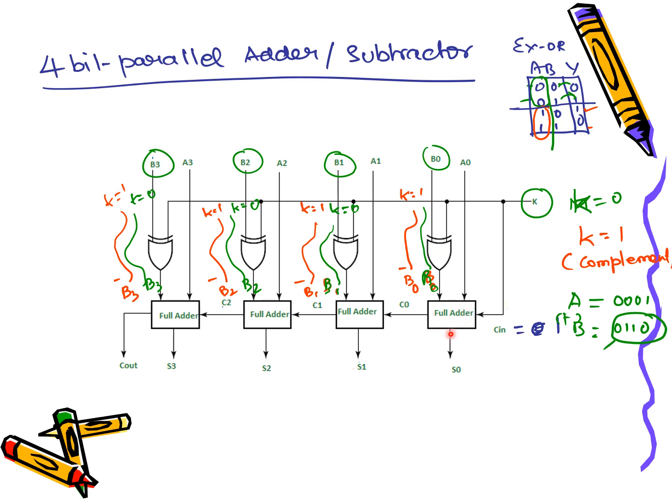So one full adder has at least 3 different gates, each of which will take its own time, say suppose 30 nanoseconds. Now imagine how many stages of additions you will have, and for that many times it has to wait to propagate and produce the final sum and carry output.